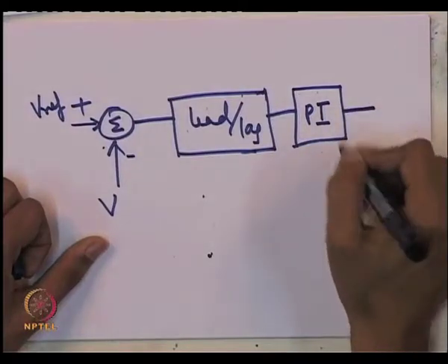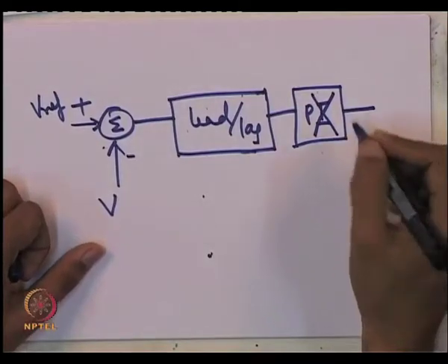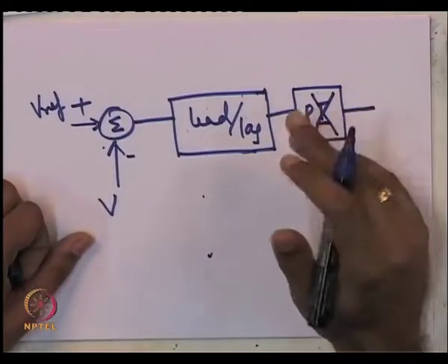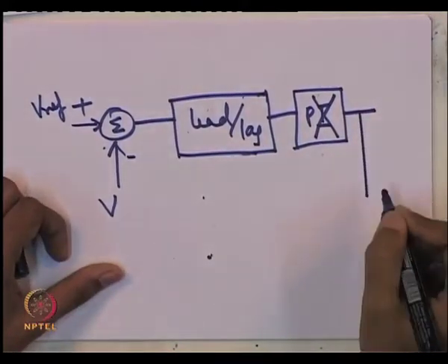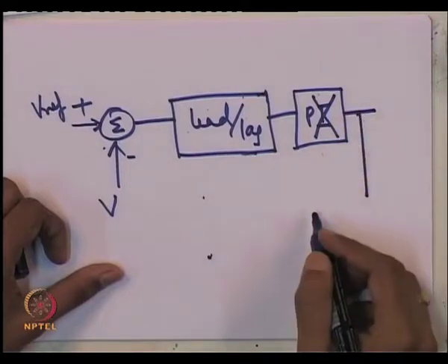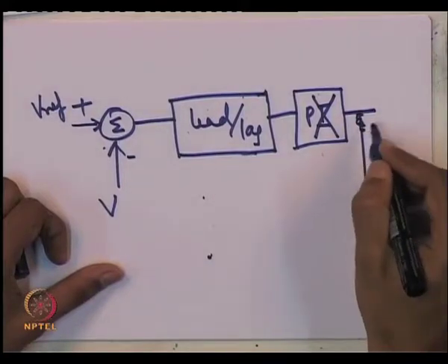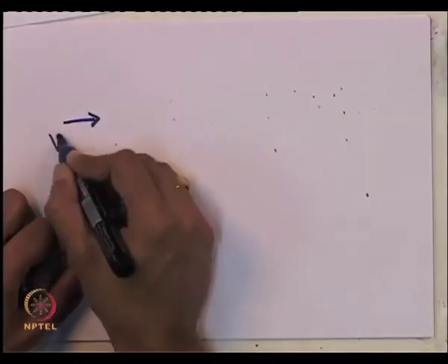And a PI controller, often you will find it is just a high gain proportional controller, integral component is absent in many kinds of AVRs. Okay. So, this is what you will normally see. I will just redraw this, what you will normally see is,